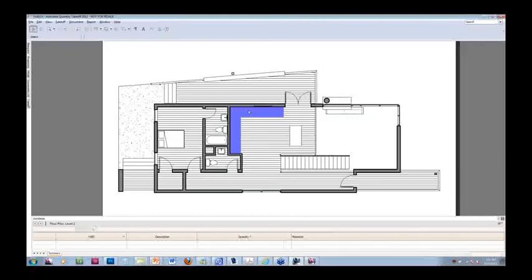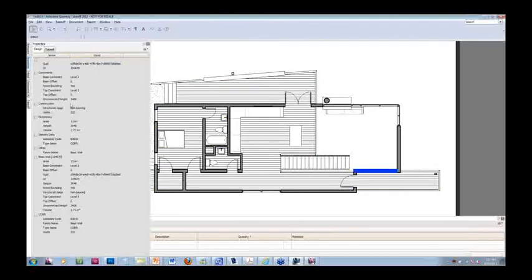So it's really cool. I mean, you can see how everything is selectable, and if you touch it, you can get information quickly from the properties about what the object is, where it starts, level 2 to level 3, what the name and type is, area, I mean, you name it. And most importantly, maybe the type and the name. So whether you go by finding walls that are based on the same name type or assembly code, or whether you're using it based on some material that came from Revit, you can use a lot of this information to select and highlight multiple similar instances.